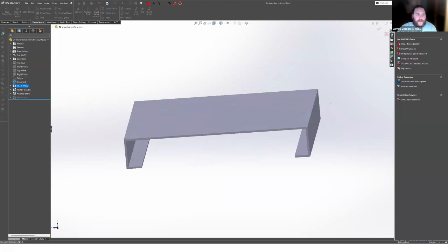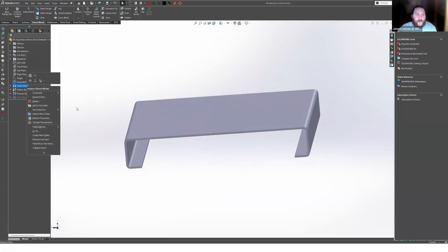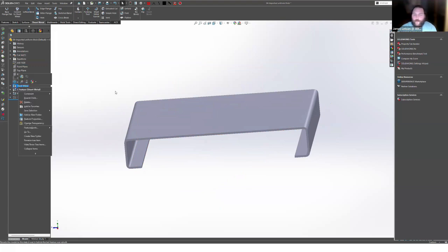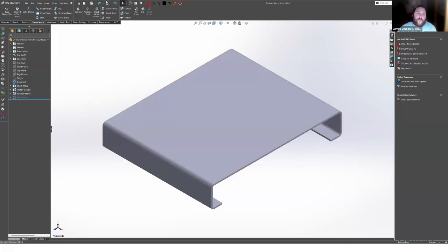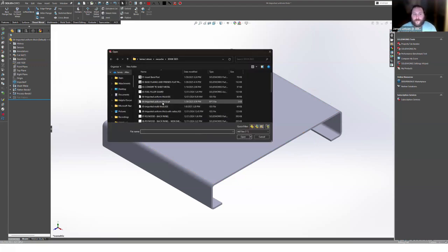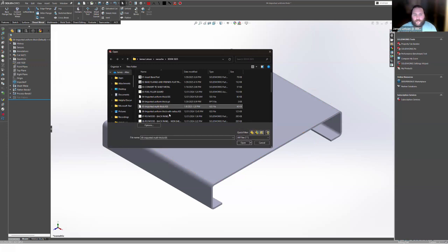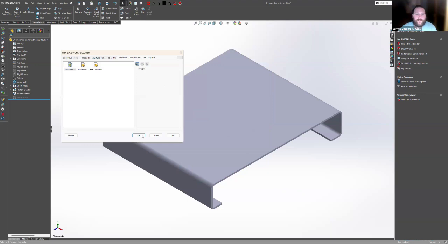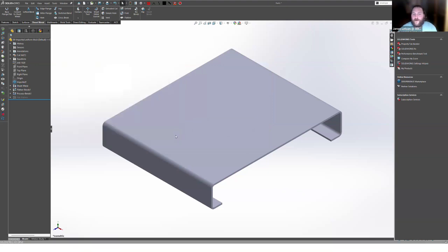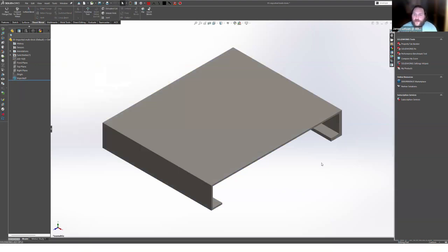And then we can change bend radius and stuff like that based off of our normal sheet metal feature, like we would on any other normal sheet metal part. So now, what if we don't have uniform wall thickness? Let's open one more part. This is another IGES file, right? And you can see pretty obviously that this part is not uniform wall thickness.